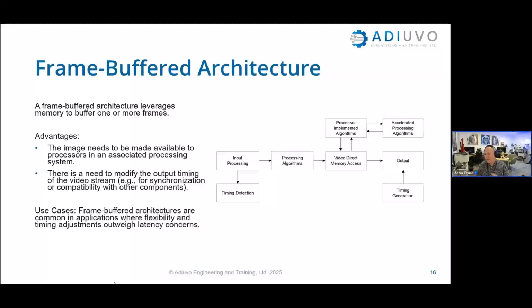Or if you've got a different size output to input, for example a 1280 input but an HD 1920 output, because you're going to put some additional information surrounding the image, you would have different input timing and different output timing. You would need to be able to generate that and get that going correctly, such that the input and the output are decoupled by this frame buffer.